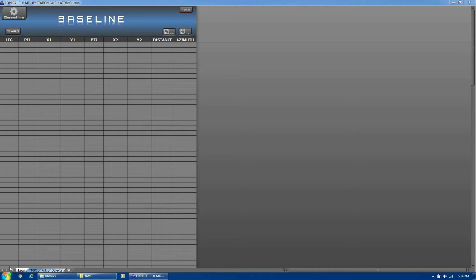The baseline is needed only if you're going to be converting station and range to XYZ or vice versa. This takes the place of a survey file. It's a little bit more advanced because a survey file can only do one azimuth. So this way you can just load in your baseline, be done with it. You don't have to keep switching survey files as you would on your dredge positioning or in the previous Great Lakes in-house program to convert to station and range.